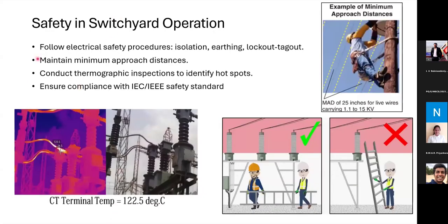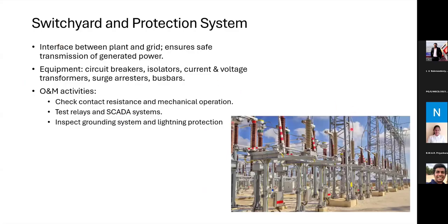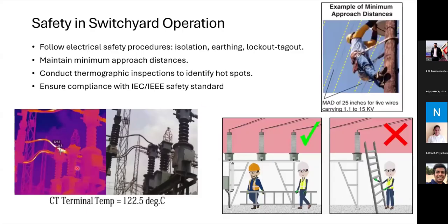So to carry out this task, since the switchyard is a region which has low hanging high voltage surfaces, basically this part is grounded, and after these insulators and the surge arrestor components, or these porcelain elements, all the surface at the higher level, we have high voltage elements. So it is still closer to the ground. Therefore, by climbing on these gantries, you can be approaching the minimum safe distance quite frequently.